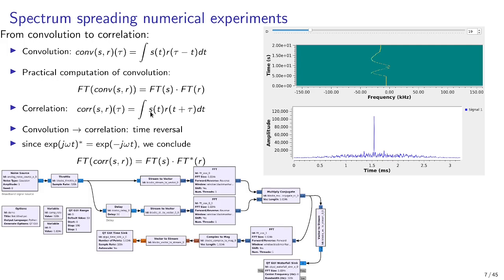The pattern detection is achieved by integrating the energy, and only if the pattern matches the signal position will negative multiply with negative, positive multiply with positive, and energy will accumulate. Otherwise, the mean value quantities will average out and the integral will be a mean value of 0. If we replace the integral with a sum in discrete time, we must sum the n elements of the code length, and this must be repeated for n possible offsets, so we have n calculations of n multiplications, or an n squared complexity algorithm.